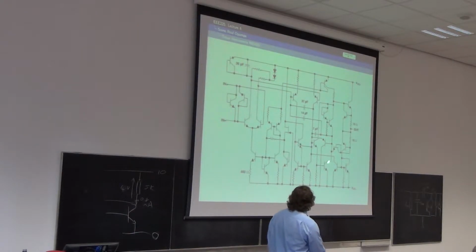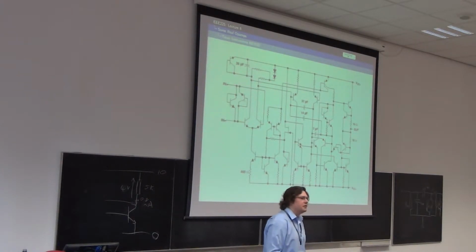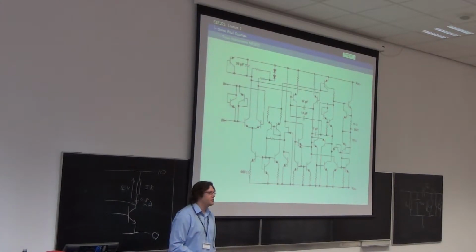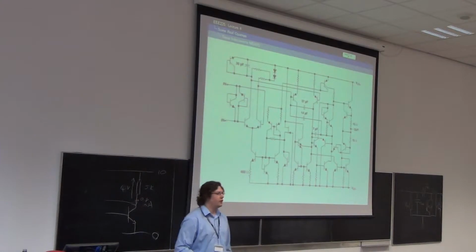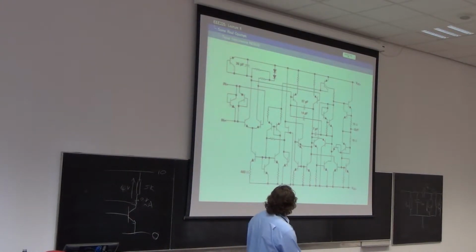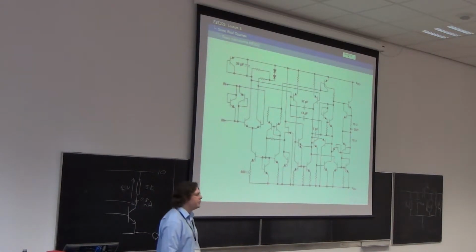And we have a current mirror here which mirrors that current to there, and a current mirror here which deals with the VAS stage. Where is the VAS stage? That's why this particular circuit is actually on the board, other than the fact that I wanted one with loads of transistors in just to freak you all out a bit. We are looking for a voltage amplifying stage. Can you find it?